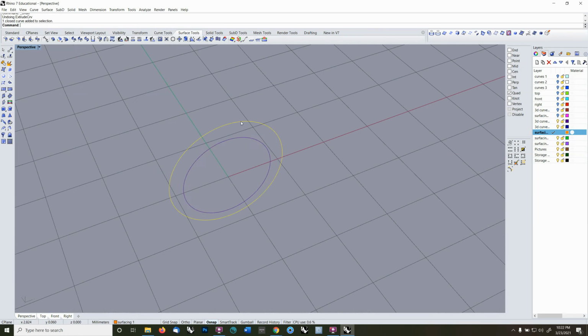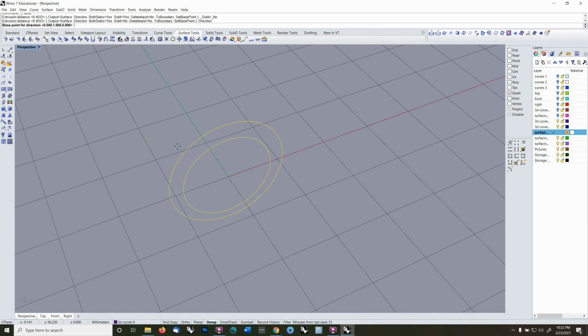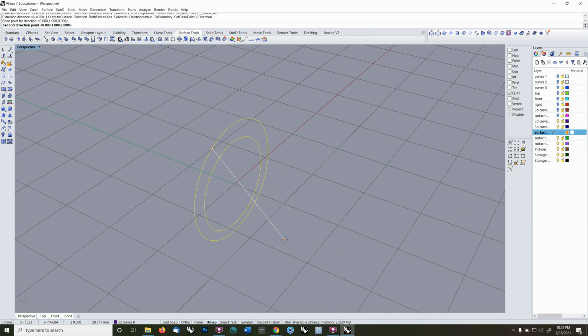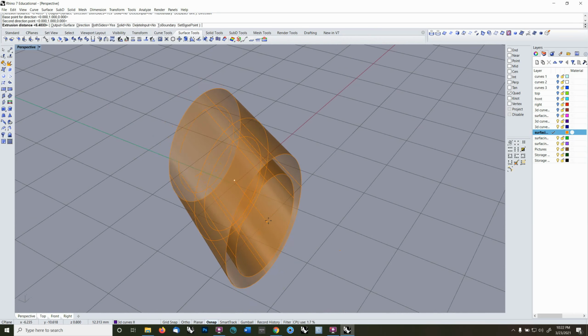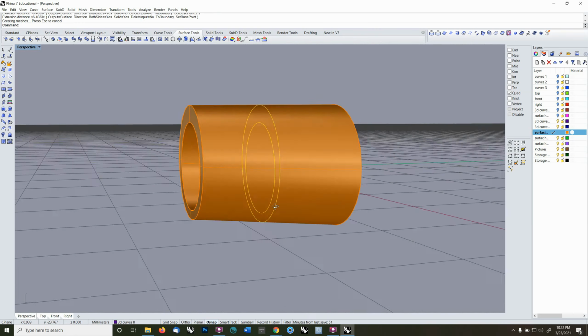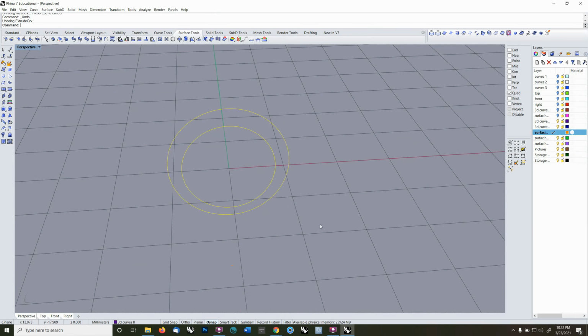Let's take a look at direction. There's very little purpose for it, but you should understand what it is. If I click direction, I can click any 2 points, because all it takes to dictate a direction are 2 points. And Rhino will make that extrusion in that direction. Okay? It's very specific. You don't need it very often, but when you need it, you need it.